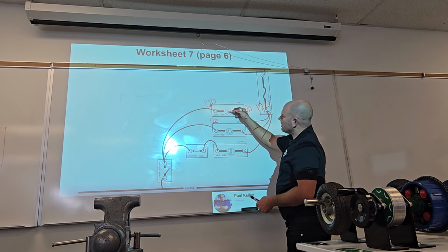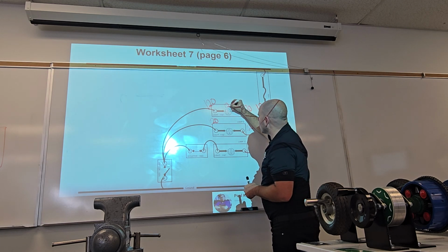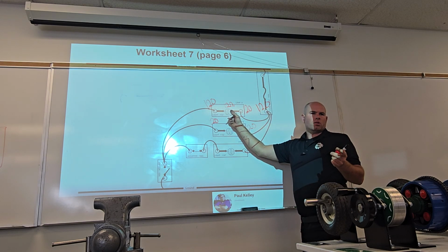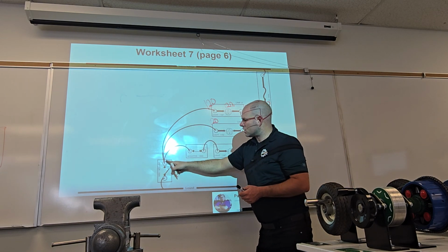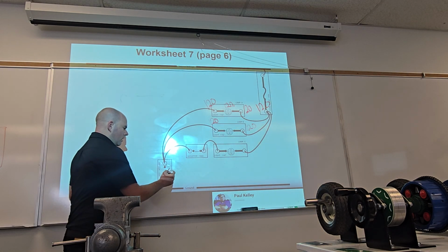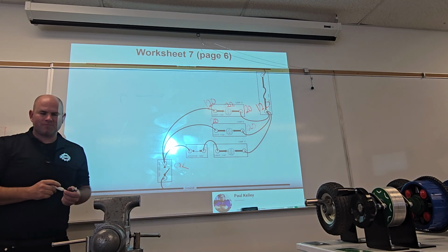This drops nothing. Even though this has resistance, we'll change the resistance now. We'll make it a 12 ohm bulb. So this should drop 12 volts. This should drop all the voltage. But if this switch is open, how many ohms is an open? Do you guys remember? On the meter, you know it would read OL, but what's that actually mean?